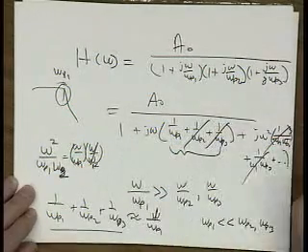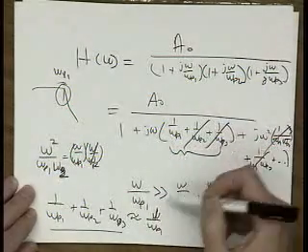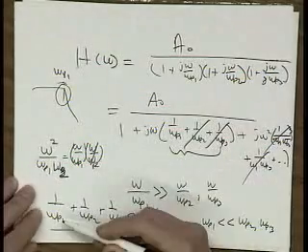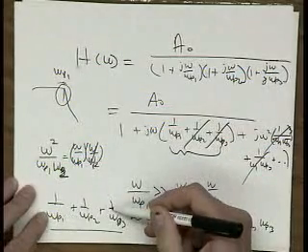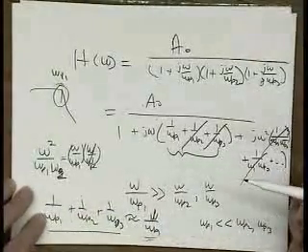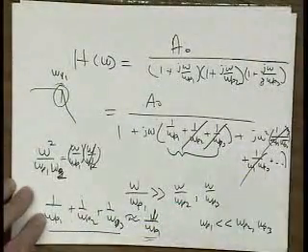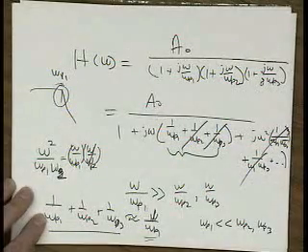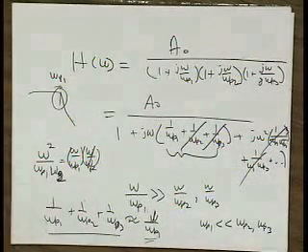So all the other terms aren't important, and by just summing the inverse of all the pole locations, we end up with something pretty close to the dominant pole, the lowest frequency pole. We call the lowest frequency pole the dominant pole. It's the first one we hit, and you'll see why we refer to it as dominant a little bit later on.